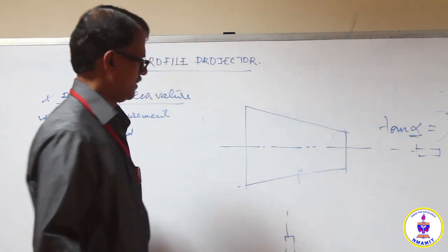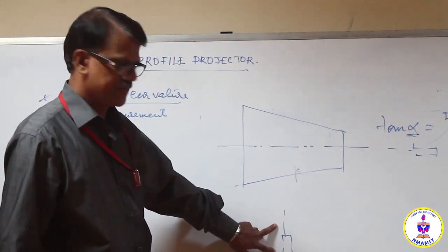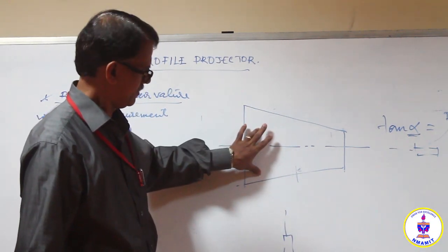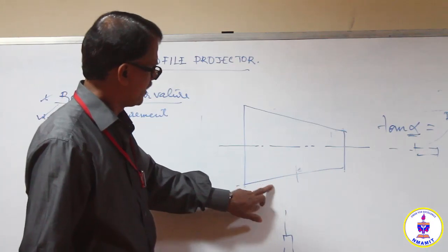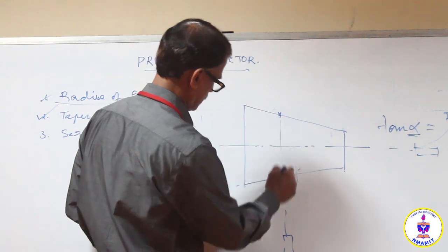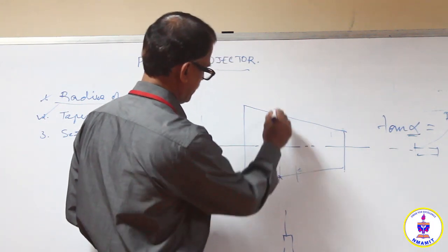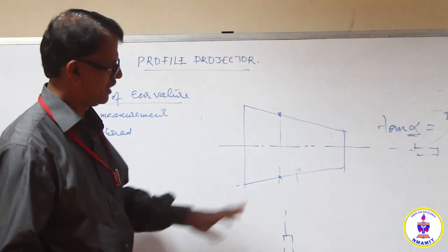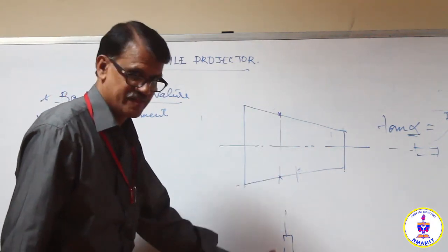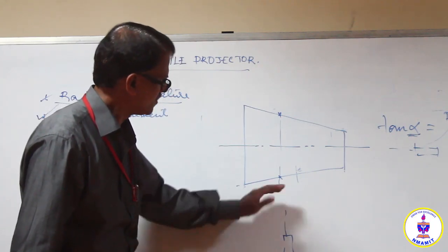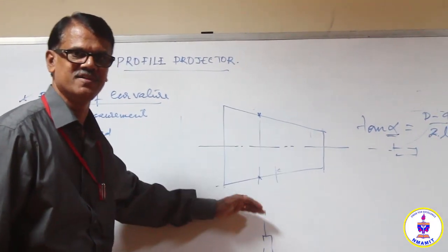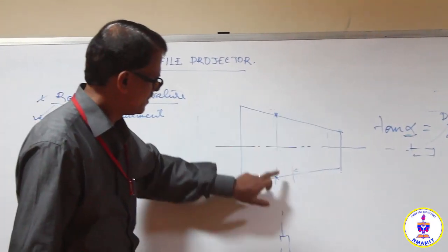Now another thing is, this micrometer has a limited range only. Now this is a larger specimen, so you have to take two readings to get one diameter. Suppose you are taking one reading here and correspondingly one reading on the other side. The difference between the two readings will give the diameter here. But when you position this one here, the micrometer is to be moved so that the shadow is moved across the crosswire here. So it must be within the range.